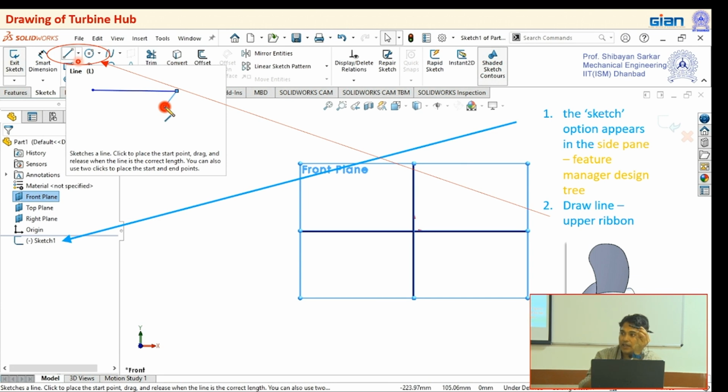In my case I have another option. Instead of cutting it in half, I am making a quarter. So I am cutting here as well as here at the middle. The axis of rotation I am cutting here, and the axis of rotation I am cutting here. So I get a quarter, and that particular quarter I will try to draw and then revolve. It will revolve about the axis of rotation and create the 3D view. So this is my intention.